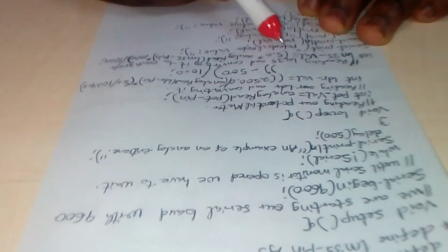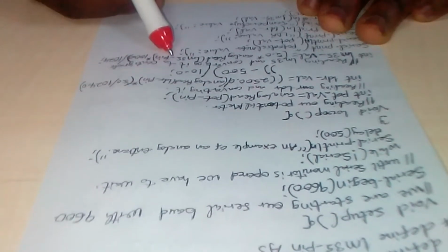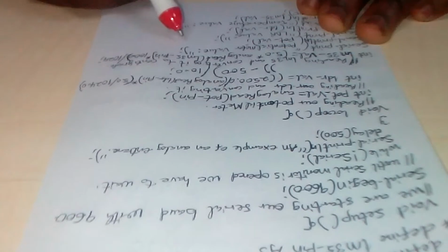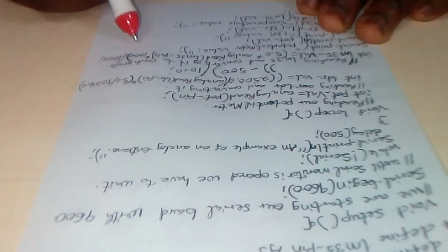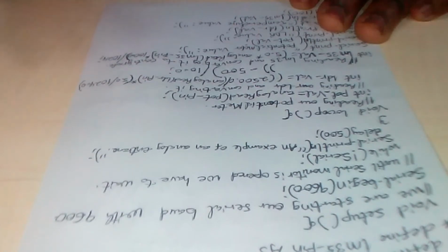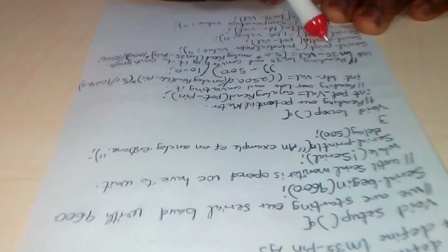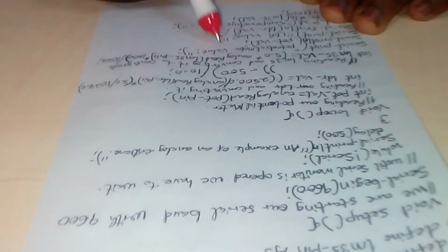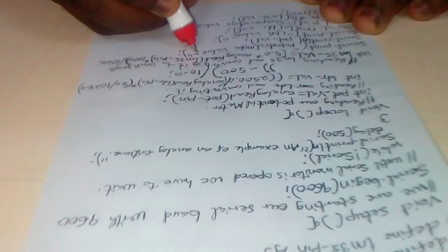Now we have 5.0 times analog read, okay, it analog reads it. Now LM35, okay, our pin, okay, times 100.0 divided by 1024, okay. With this, that actually means we have converted our analog into digital. Now we can print it on our board. Now we say Serial.print, okay. We say potentiometer value, okay. We're going to print our potentiometer value as a digital.